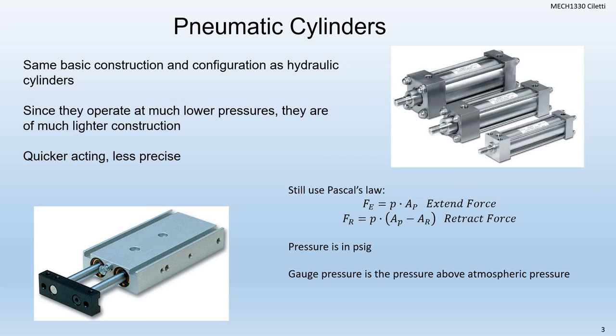So a lot of stuff in this chapter. We're going to be doing some duplicate stuff that we did with hydraulics, so I might brush through that real quick. Now, since they operate at much lower pressure, they are of much lighter construction. Not quite as heavy duty on the pneumatic cylinders as we are with the hydraulic cylinders. However, they are quicker acting and they are less precise.